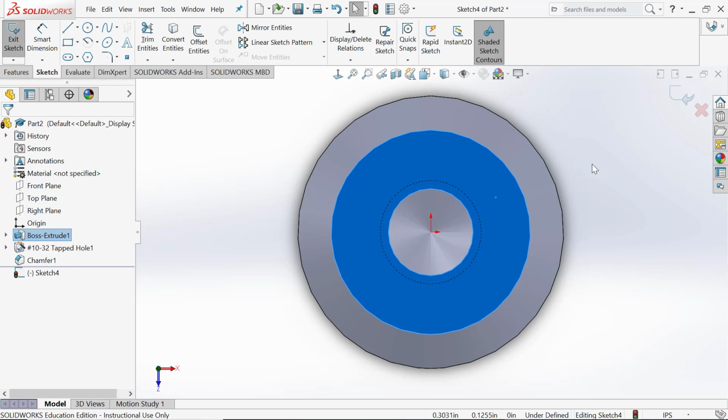Wait. Is this fillet wrong? I got inverted. His went in instead of out. I don't even know what that means. I think you got the top, we got the bottom. He added material instead of removed material? Like he added a ridge around it? Instead of clicking the edge of the actual circle, we clicked the edge of the inside circle. Right, so that's pretty easy.